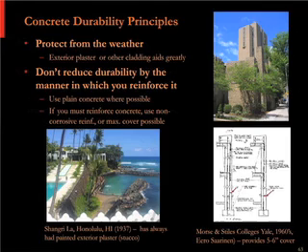And Saarinen, what he did there, he was using a kind of granite boulder facing that was cast into the concrete walls. So that was his way of being sympathetic with the traditional architecture of Yale. But as a result of that, those stones are 5 or 6 inches deep. The steel was set 5 or 6 inches deep behind the concrete. So instead of the typical 1.5 inches of cover, he had 5 or 6 inches of cover. And that's really what's made that building hold up so well, because the concrete quality is very similar to the other buildings I've looked at. So it's really the cover that makes that building in better condition than all the others.